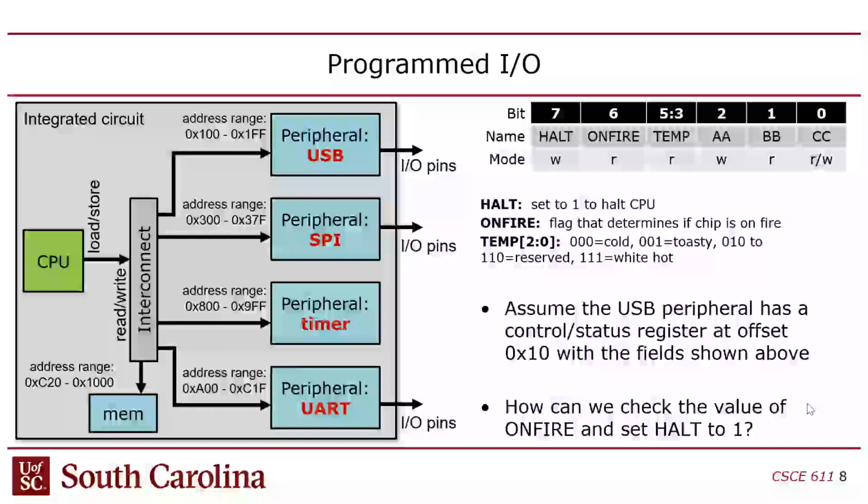These control and status registers are generally split into bit fields, right? In other words, you take a register that is matched to the native word size of the processor, and then it's split into fields, kind of like an instruction is. You guys remember from 212 when we looked at instructions.